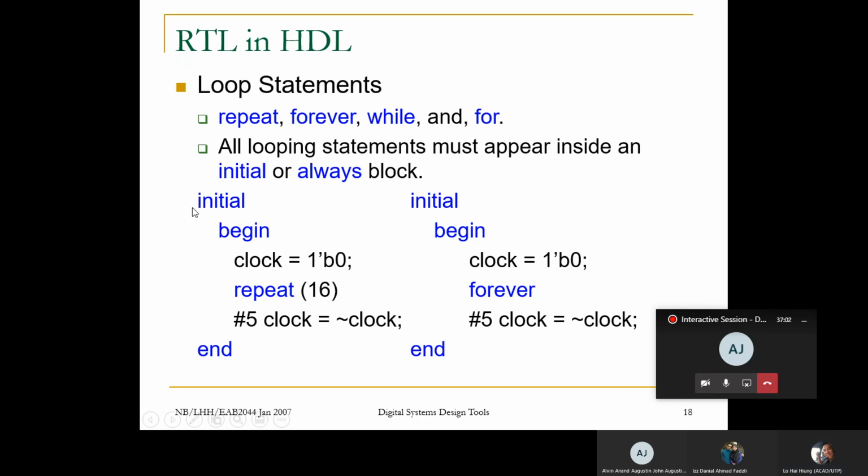First, when you see initial, the initial statement is a non-synthesizable statement in Verilog. That means anything you write inside an initial block cannot be translated into hardware. So any initial block is non-synthesizable. So it is a bad idea to use an initial block coupled with a loop statement to design your hardware.